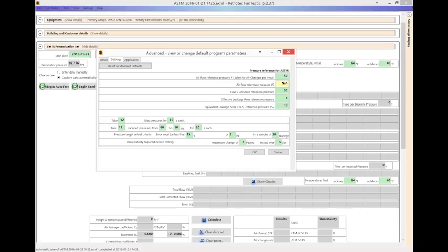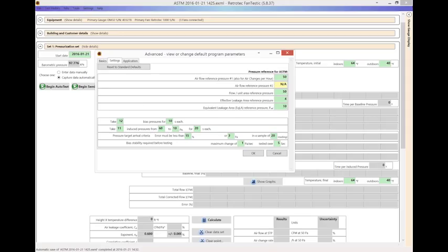On the upper right here is from basic stuff as to, do I want to measure my air changes per hour at 50? A lot of these are just kind of given. I don't really change any of the parameters that are usually on the right side here. Sometimes you may actually get other systems where you're going to reference 75 pascals. European standards may have something that's completely different, but in general, for the ASTM, we're referencing 50 pascals.